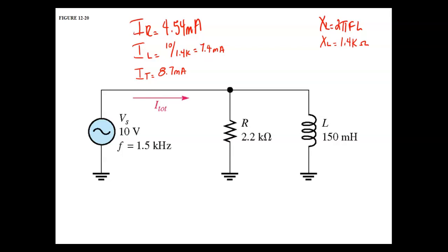Especially if you get into transistors, guys. They give a rating on a transistor called a beta, and they give you the minimum beta. So that means that's the minimum current gain you should expect. They don't tell you the maximum. It just says you should expect the minimum. So one of them might have a gain of 80, and the next one right beside it might have a gain of 60, and they might be exactly the same part number. So we usually use the circuit to set the beta.